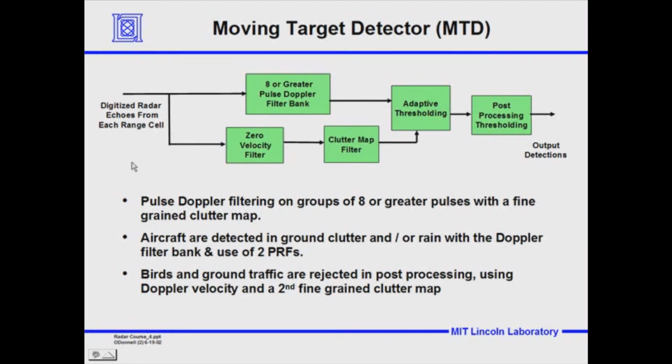Now, back in the late 1960s, an MTI processor would be implemented, and you'd divide the radar coverage up into segments of, say, 22 degrees by 25 miles or something. You'd either have just the normal video unprocessed without an MTI, or you'd process that whole area through an MTI process.